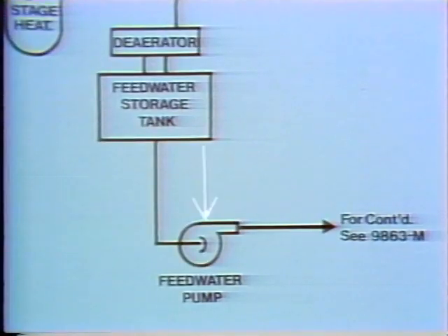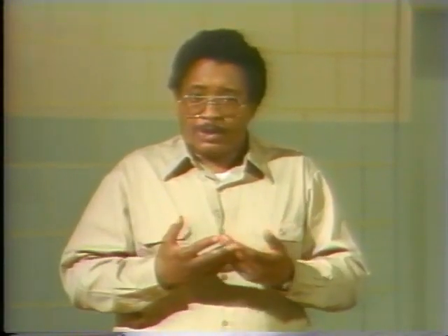Finally, a feed water pump draws water from the feed water storage tank and sends it through the feed water system to the boiler. Now, the point where the condensate system ends and the feed water system begins varies. The P&ID you use will tell you how your plant's designed.